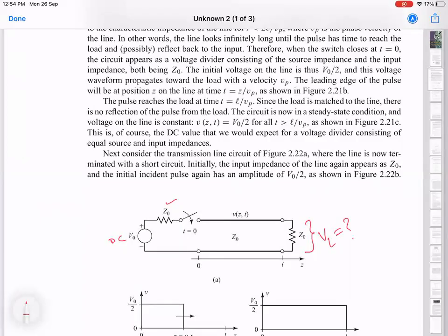Yes and no, but you're thinking in the right direction. What is the role of the transmission line at DC? It is just a resistor, I think. It's just electrical length becomes zero. Electrical length becomes zero. You are saying it becomes a resistor of value Z0. Anybody else? Are you talking about only the transmission line or everything else? So let me be more explicit.